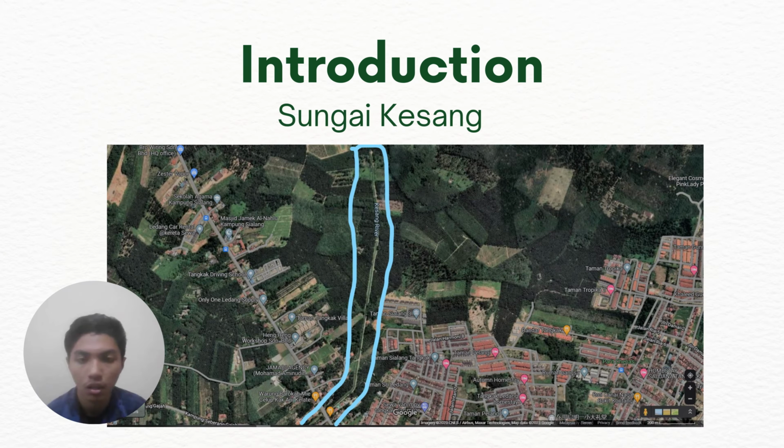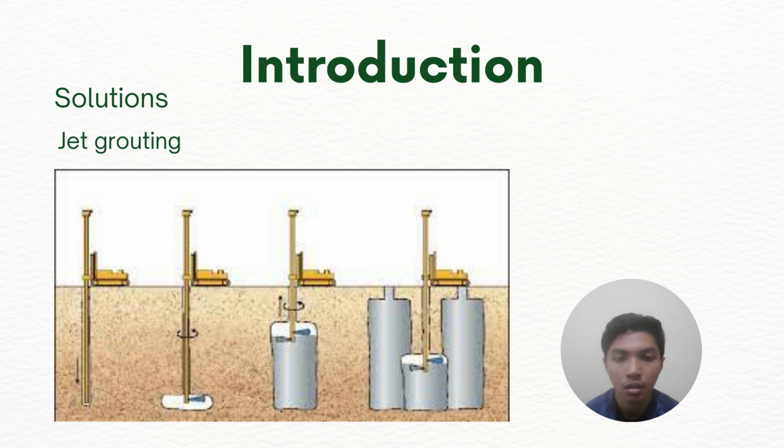For the next solution, an engineer may use the jet grouting technique. It is a bit different from micropiles, in which jet grouting will dig the cylinder first and fill it with concrete. We can see from the graph, jet grouting is usually bigger than micropiles, whereas jet grouting is used at certain places, while micropiles are used at many places, with them being more in numbers.